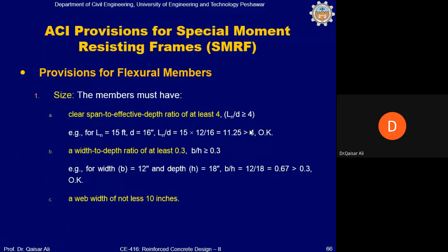Failure due to flexural stresses and flexural cracks is more desirable than shear failure. For this reason, we would like beams which are part of the special moment frame to fail in a flexure mode instead of a shear mode.